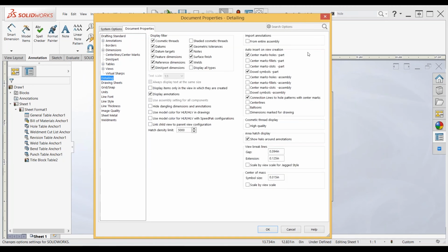And now that this new view exists, I can snap between my full screen by clicking that button, all the way down to my title block with just one click. So I can snap between those views very easily and very quickly. I'm going to make another one up here for my bill of materials. So I'll call this bill of materials.